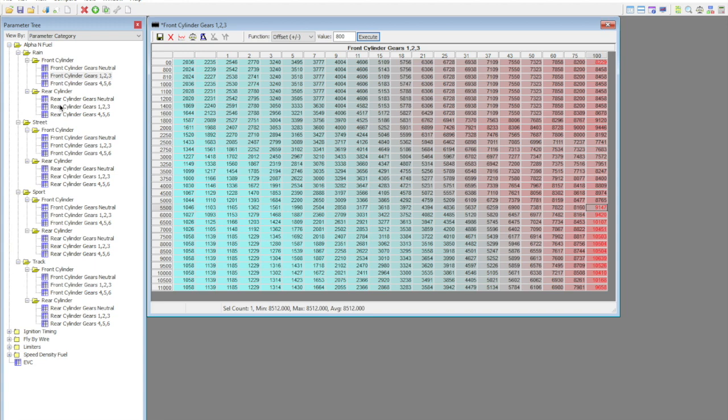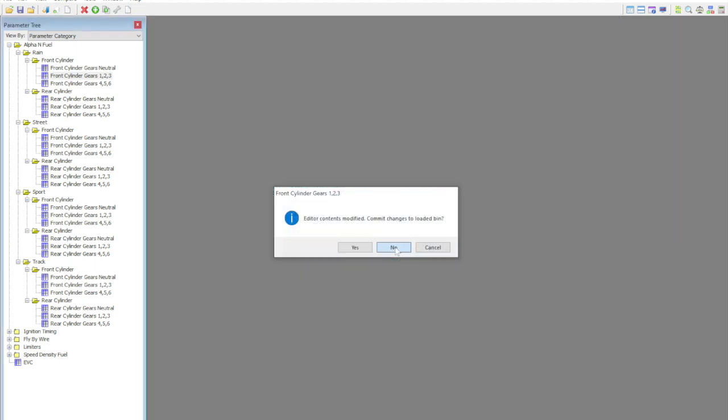So again, the most important thing with tuning is making sure you have the right information, and you need to monitor AFR individually per cylinder. Good thing is, it's only a twin, right? It's only 2 times you have to do that. Imagine tuning a 4-cylinder like we do, like our Aprilia V4s, Ducati V4s. We have to tune each of the 4 cylinders individually. That takes 4 times as long, but it results in a proper tune. So let's go back to this. We have the idea of how fueling works, right? Don't need to make those changes.